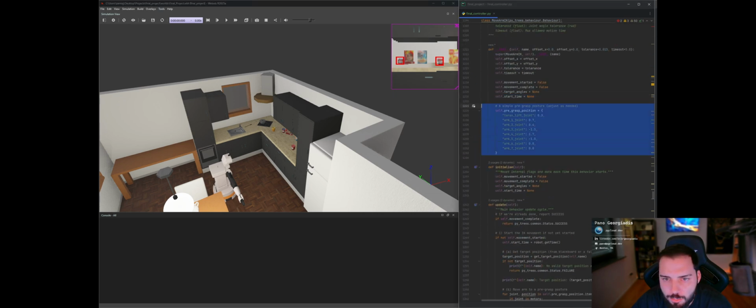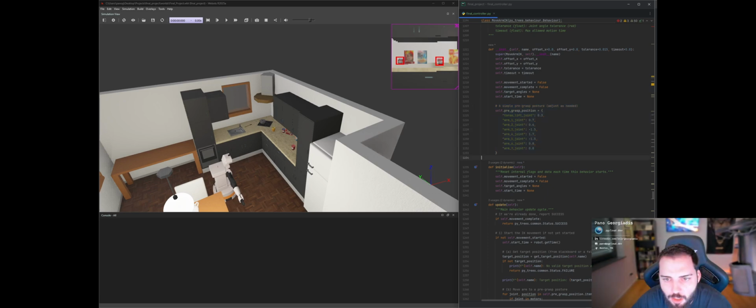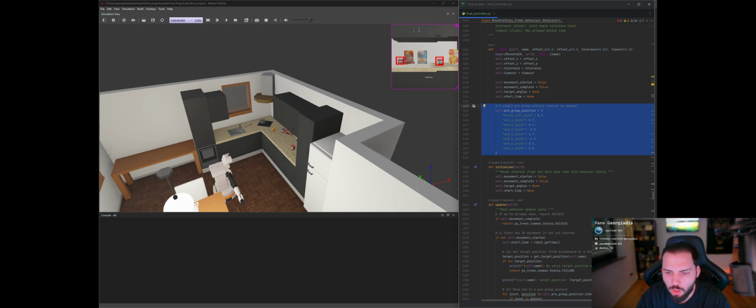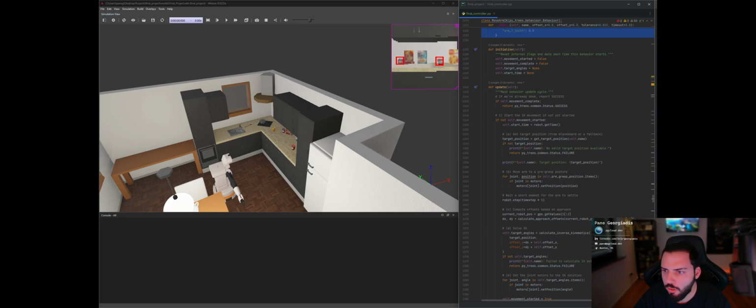And then you can see this pre-grasp position is in there. This was through trial and error and much frustration. I figured out that you cannot just have the arm wherever you want it to be and then calculate the inverse kinematics when doing it multiple times in an environment like Webots. You want to make sure that the arm is in the exact same starting position each time it goes to approach an object, ensuring that when it's calculating the inverse kinematics, the end effector is going into the exact position that you want it to go into, and that there's no leeway for any joint positioning errors.